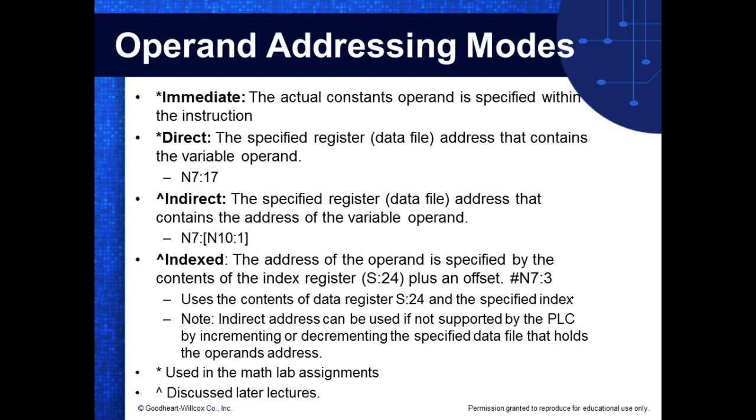The only thing that we can't get to is your inputs. So if I was using an input word, then I would have to bring it in with a move instruction first. That's the only difference, because that's considered outside stuff, right? So yeah, we could bring this in from a thumb wheel switch. We could bring it in from a push button. We could bring it in from, like you said, the results of a previous math operation.